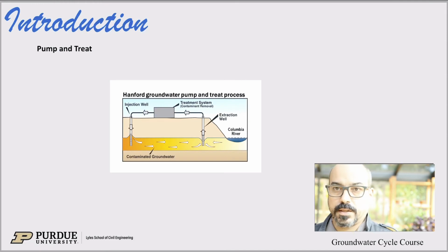Finally, the pump and treat system. And again, we'll talk about dewatering and pump and treat towards the end of those lectures here in this module. But pump and treat is another usage of wells, where you pump water that has been contaminated. You decontaminate, so you clean it up in some above-ground facility, typically. So you have something to clean the water on the top, a water treatment facility.